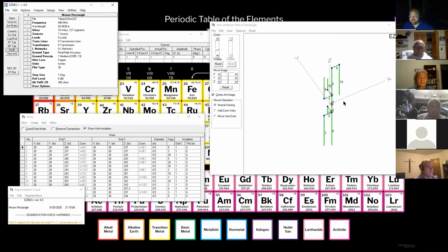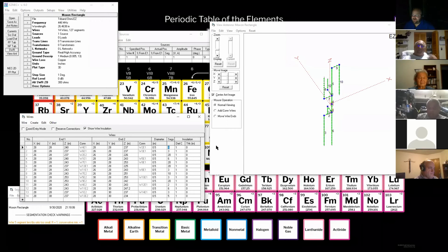All right, any other questions? Yes, I have a question. Go ahead, Jim. The segment numbers, that's how many you break each line up into, right? Correct. So each line, it's going to take measurements this many times along the lines. So that's the segments. You can consider those little wires that make up a longer wire. The more segments, the more resolution you get.